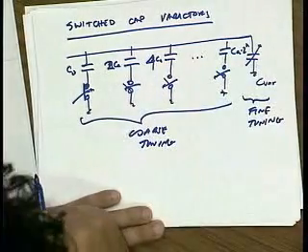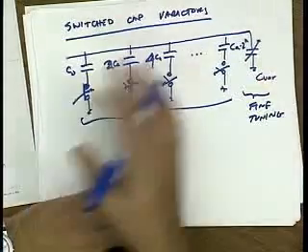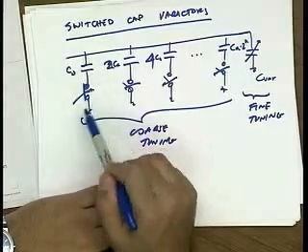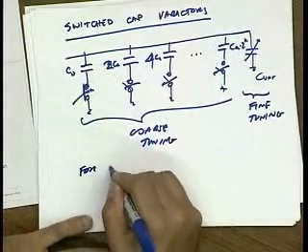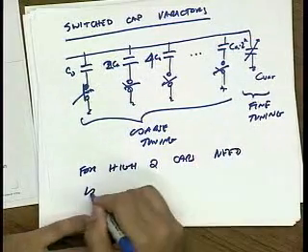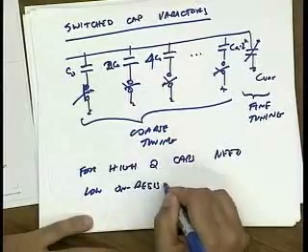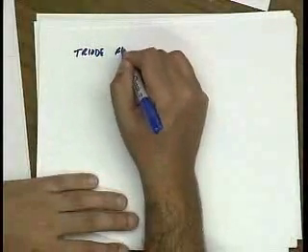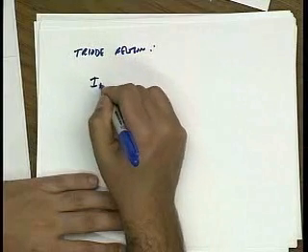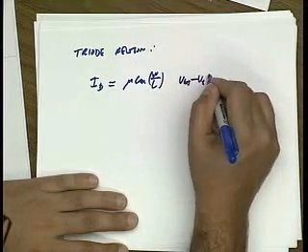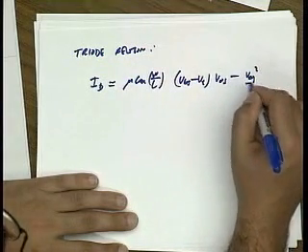What's interesting is you might think, well, why is this a new idea? By new, I mean the past 5 or 6 years, maybe a little bit more. The reason is that these switches have to have very low on resistance. So for high Q, you need low on resistance. And the on resistance, basically in triode region, the current is approximately mu Cox W over L, (VGS minus VT) times VDS minus VDS squared over 2.